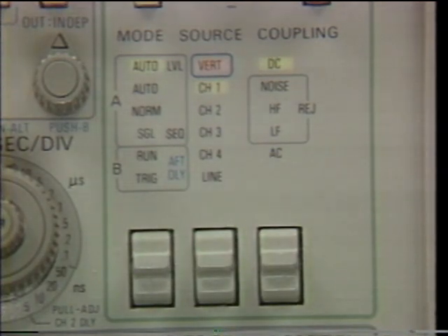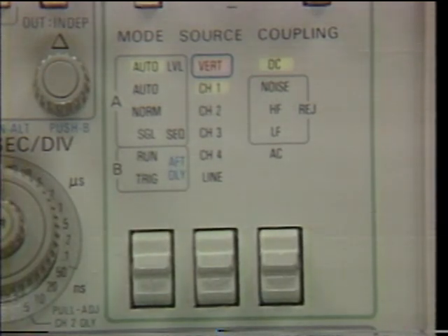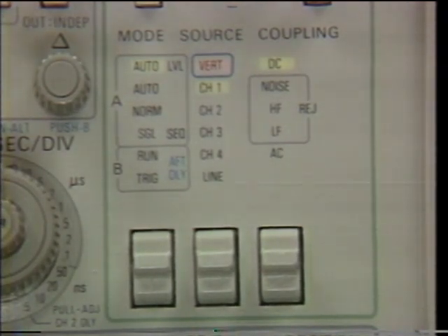Let's now take a look at the various coupling selections. DC coupling is the most often used selection. In this instrument, the trigger signal is independent of vertical positioning, so this is now feasible. The advantage of DC coupling is that it provides the most stable trigger with the largest variety of signals, especially digital signals with varying duty factors. DC coupling also gives us a trigger level readout.